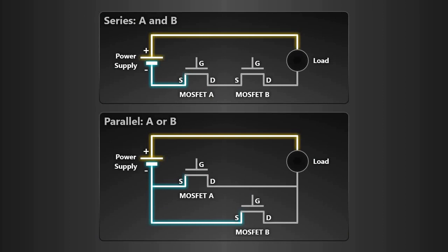The trick we use to make gates is as simple as putting transistors in series or in parallel. Let's examine two circuits. A gold glow on the wires denotes a positive voltage, whereas the aqua glow denotes a negative one. In the top circuit, two transistors are put in series in a circuit containing a power source and a load, such as a lamp or a motor. If both transistors are off, the continuity of the circuit is broken and the load cannot get any power.